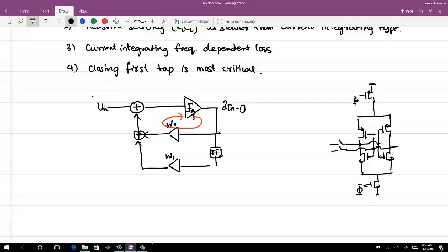So this is one comparator which you use, where the input is sampled. Input is V in. Input is sampled in one phase at these cross coupled nodes. Let me call them VOP and VON. Okay, this is just a very bare comparator. And input is sampled on VOP and VON in the phase when the clock is low, and when the clock goes high, these inputs are allowed to regenerate. There will be a reset switch which I have not put, but this is the basic functionality.